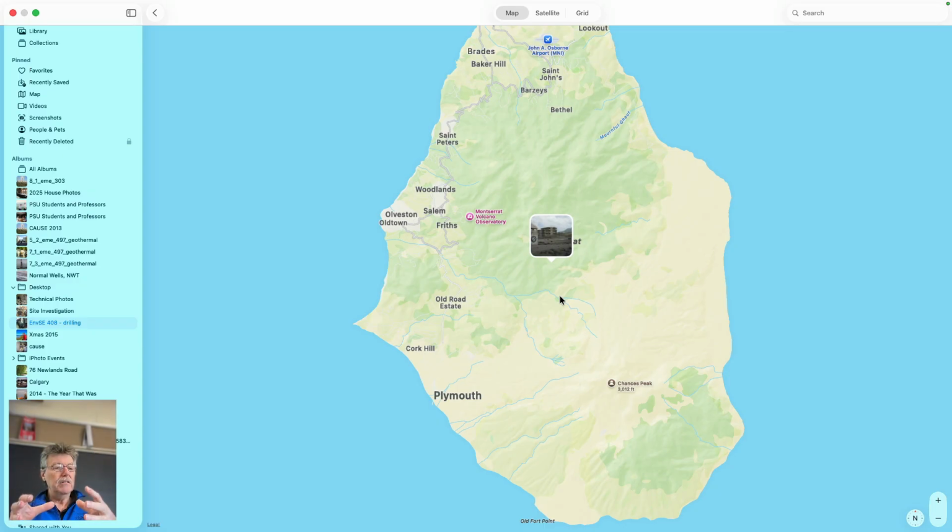And so you'd pack it back with sand around it so it was held in the hole because you want to retrieve it later. And then you'd hydraulically frack your site in the oil industry, in gas, and this would deflect. And you'd use that deflection to calculate the whole deflection over the surface, hundreds of meters away from the borehole, and be able to predict exactly where your hydraulic fracture was going. So that was the technology that was used there. So a strain meter, a tilt meter, and a seismometer.